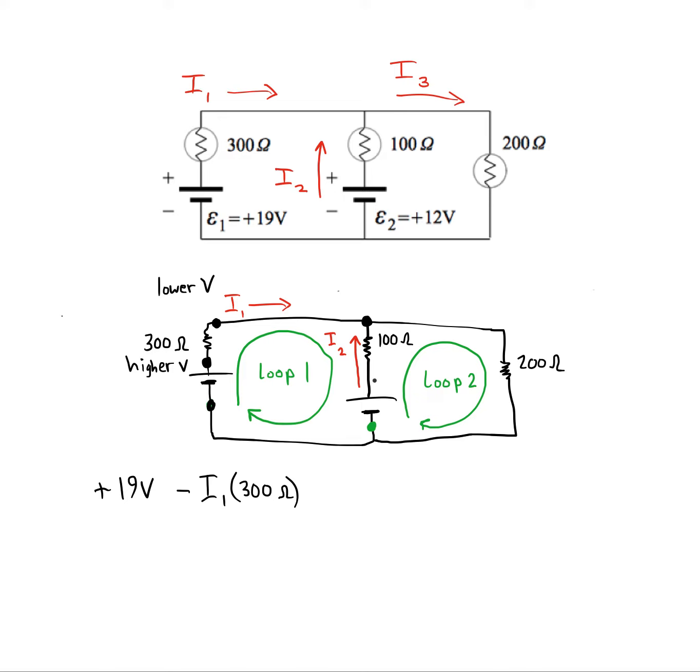This point above the resistor, or this point below it? Well, since current flows from high potential to low, we have to assume that this is a lower potential than this point here. So we're going to gain potential as we move through that resistor. You have to imagine what it's like taking a trip all through this circuit. How does the potential change? Well, it's going to go up in this case.